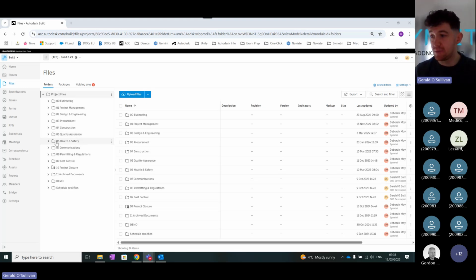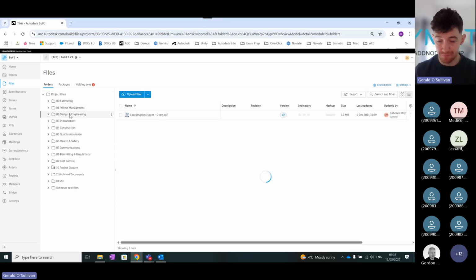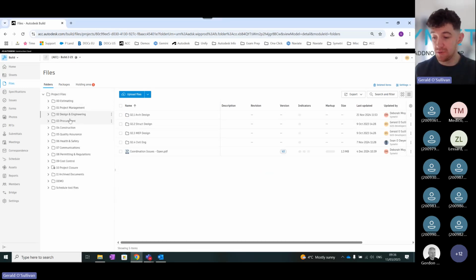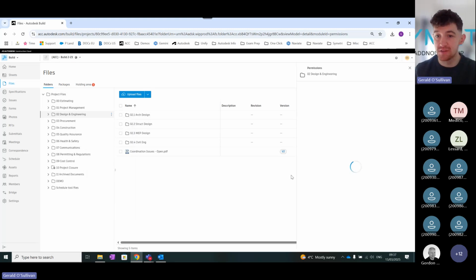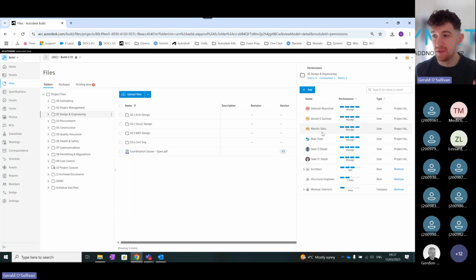And with that, as you probably already know, within these folder structures, depending on where you're going, someone is the main contractor on this project, and you're inviting in other subcontractors to work in your environment. The key thing with that is that you have one single source of truth, and that people are working in the areas that they're meant to. How you can control that inside here, again just to summarize, is you can click on the 3 dots, go to project settings, and control what visibility people have within this files area as well.